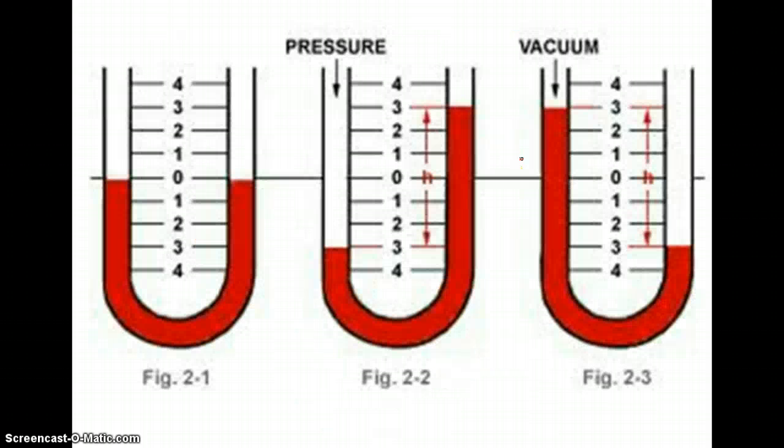What this looks like is, if there is no change in height and we're looking for the pressure of that gas, we get the initial pressure plus density g h. There is no change in height, so this term goes to 0, and that has a pressure of 1 atmosphere, right? And we can also talk about that in terms of pascals if we want. If that pressure is pushing down, that liquid goes up, and I have a positive H, and so that's going to be a pressure greater than 1 atmosphere.